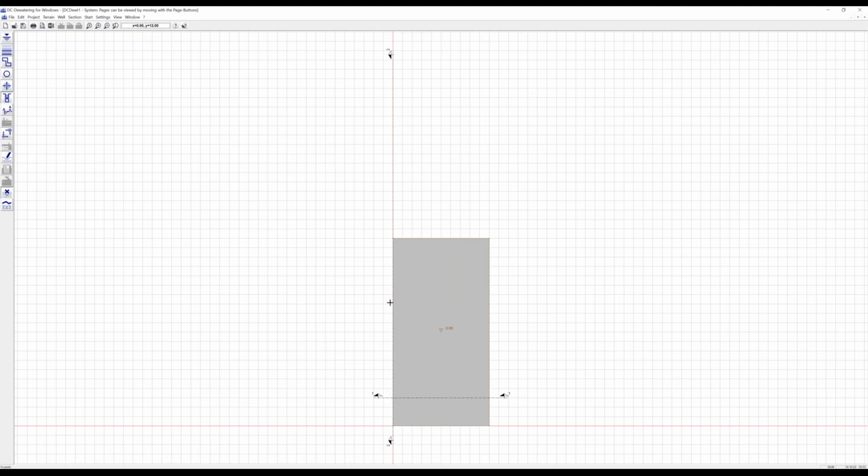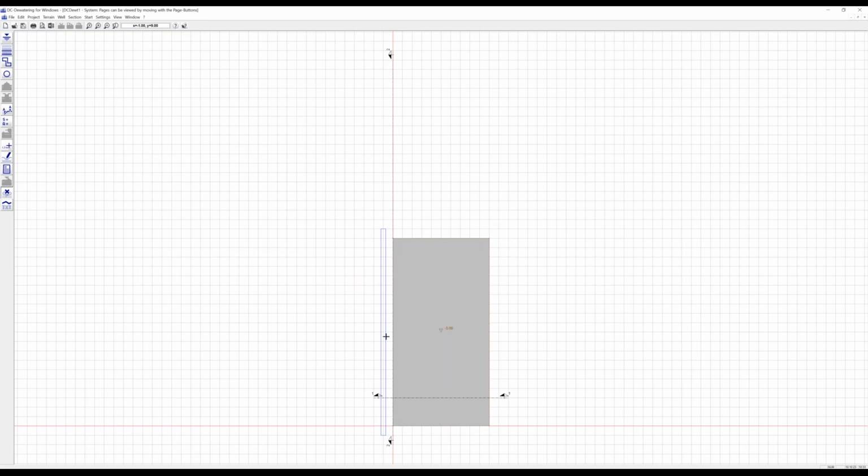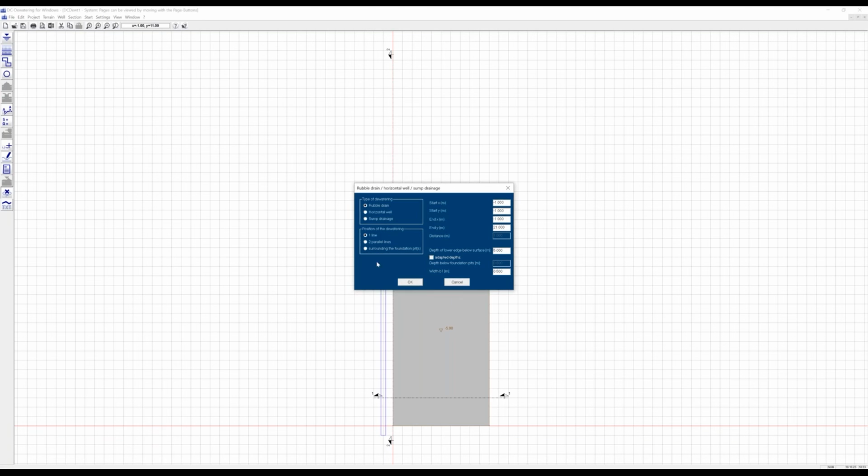One is that we just have one line of horizontal well. So it is one line at one side of the foundation pit. This is mostly used if there are very long and thin foundation pits. So we can work with one line. As an option, we can use two parallel lines, which have a certain distance. This would be 12 meters here, for example.